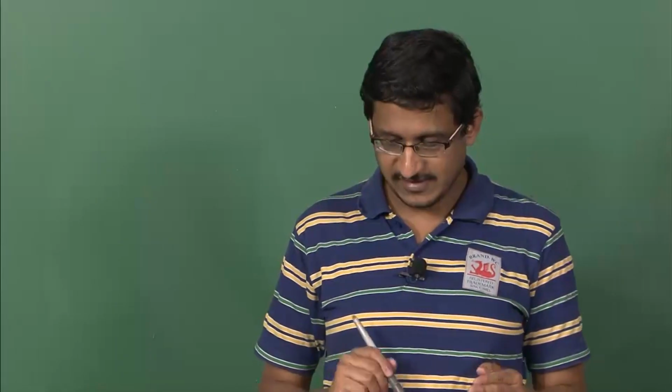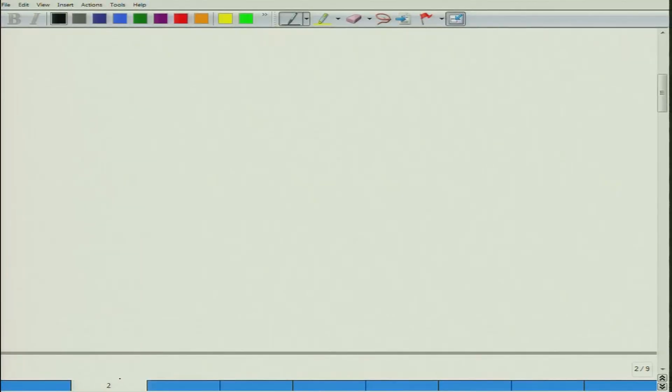Okay. So, having said that, now let us try and evaluate what is this delta P by delta z. Well, on the left wall, what is the tangential H component that you are going to obtain? That would be the Hz component, right, on the left as well as on the right wall.